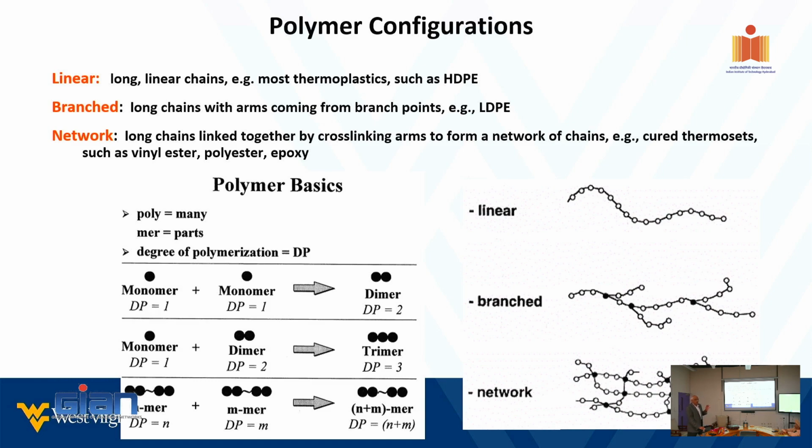Okay, why, what's the issue here? You see that here. In a thermoset, it is cross-linked, that's the word we use. In a thermoplastic, it is linear or branched. So this is exactly why: the cross-linking is difficult to break. It can be broken, but only under certain conditions. So if you can break it, you can recycle it. If you cannot break it, you cannot recycle it.